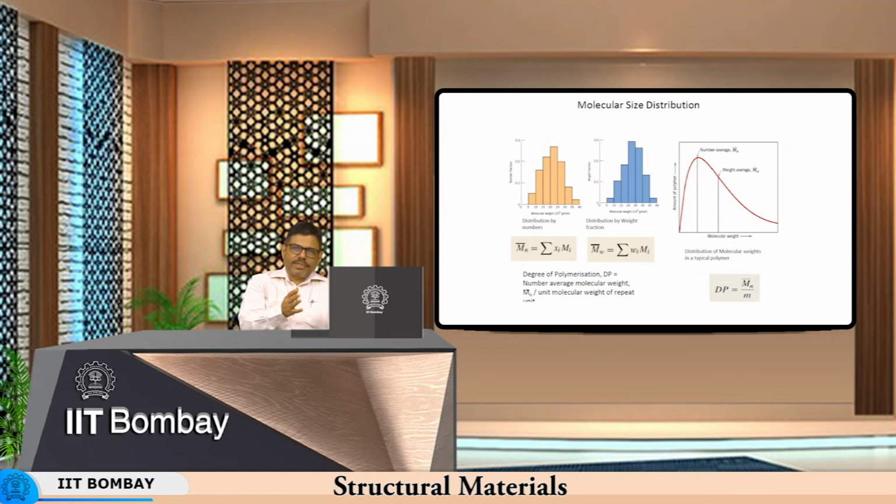Whereas in case of metals, if I say that I have an alloy of a particular composition, the alloy will melt at a particular temperature. So, at the liquidus temperature it is going to melt, and anything higher than that it is always going to remain molten. But in case of polymers, that does not happen, because you have molecules of different weights present in the polymeric granules, due to which some melt, some do not melt at a given temperature.